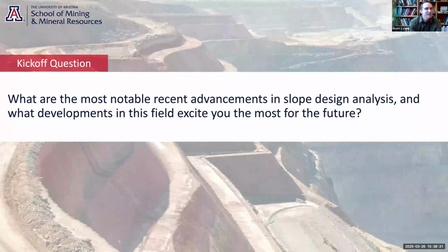So the two big advancements that I've seen there are, number one, when we run limit equilibrium analysis, we can now put in something called the anisotropic line. And what that is, you draw a line into the model, and it can be any shape. And the anisotropy that you put in will basically follow that line throughout the model. So it's really, really nice for bedded deposits or deposits where you have a lithology model where everything is deformed, because now you can have your anisotropy follow that.